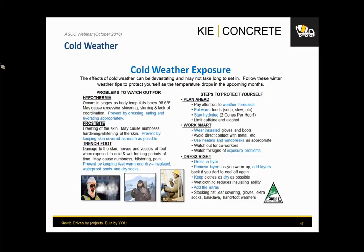You want to make sure of some of the key things. You want to make sure that you understand how you're going to provide curing to this concrete, right? You want to know how you're going to protect the concrete from the cold, right? How you're going to insulate it. Do you need to provide layers of insulation? Do you need to provide any type of heaters,